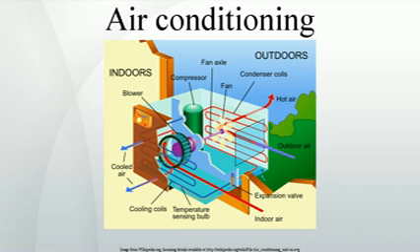Ductless split system air conditioning. Mini-split systems, today usually called ductless air conditioners, typically produce 9,000 to 36,000 British thermal units, 9,500 to 38,000 kilojoules, per hour of cooling. Most ductless systems are similar to PTAC air conditioners in that they are often designed to cool a single room or space, but ductless air conditioning allows design and installation flexibility because the inside wall space required is significantly reduced and the compressor and heat exchanger can be located further away from the inside space, rather than merely on the other side of the same unit as in a PTAC or window air conditioner.